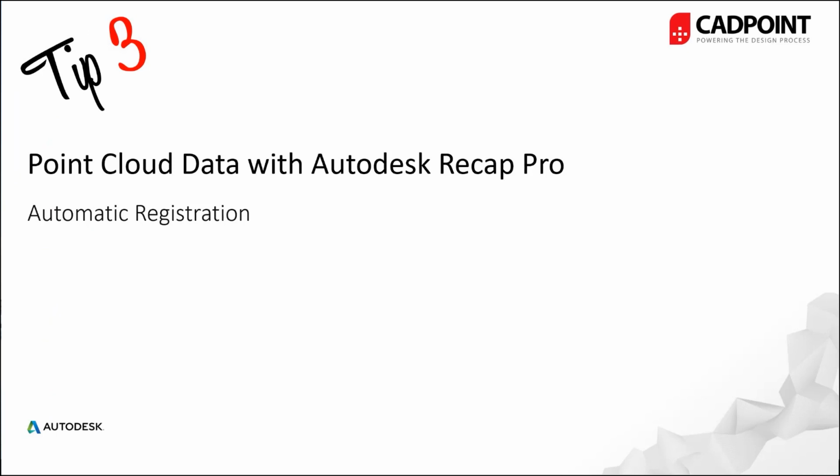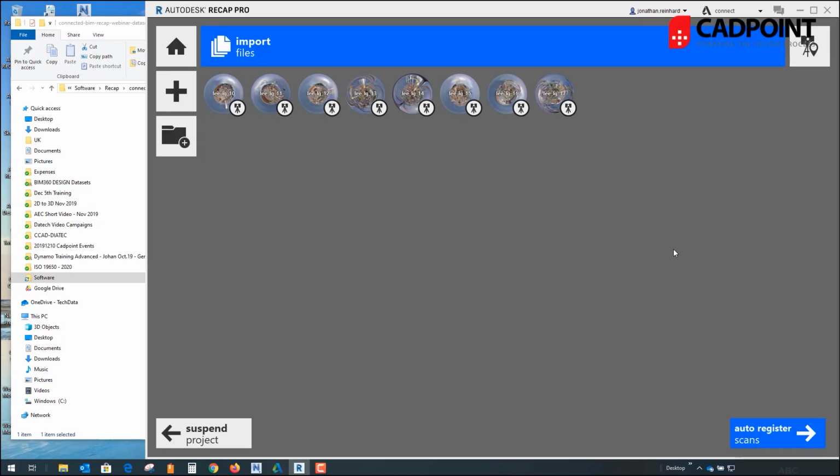When you're launching your project and registering your scans, it gives you 2 options. One is skip registration and the other is manual registration. What registration actually does is combine all of the 8 different locations of your surveying equipment. If you select manual registration, you're going to have to do a certain amount of manual work to line up all of those 8 different captures. Because when you think about it, it's 8 different cloud files, and what the registration does is line them up using the targets that were placed on site.